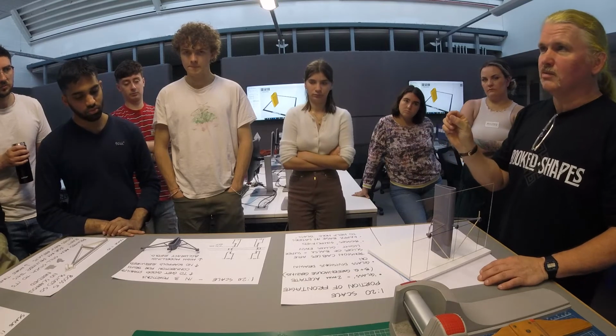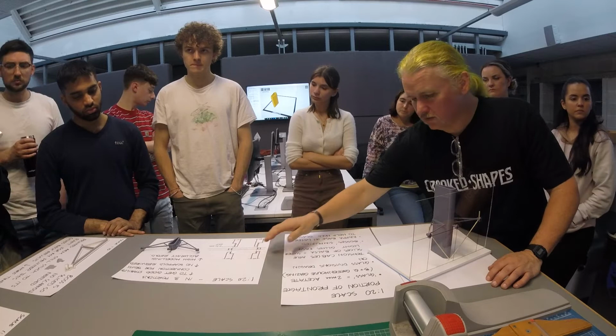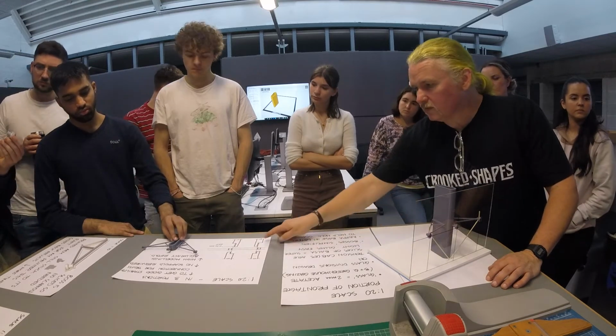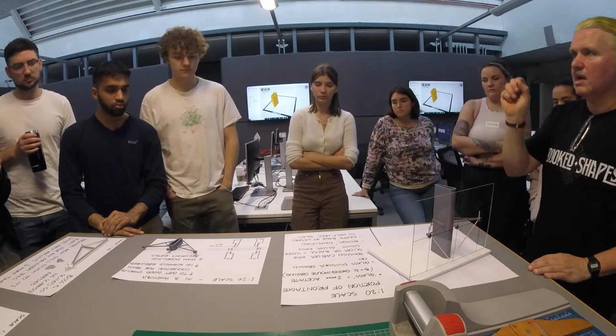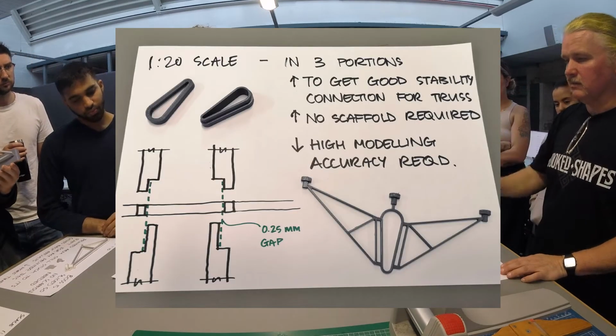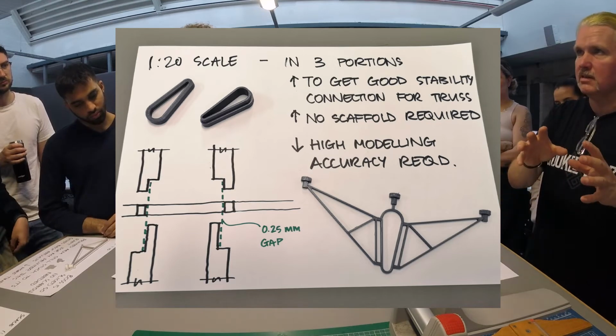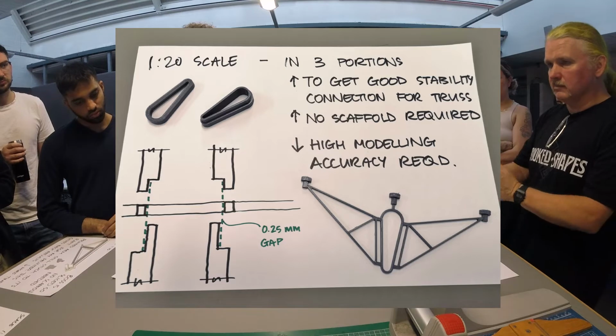You know, 1/4 of a millimeter is, you know, virtually nothing. So that's the kind of detail through there where you see that there needs to be a gap. There needs to be a tiny little bit of airspace, and that's where the CAD accuracy comes in. You know, if you've not got the accuracy in the drawing, you can't get that through into the model.